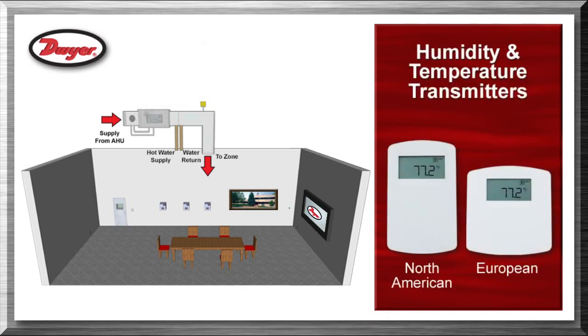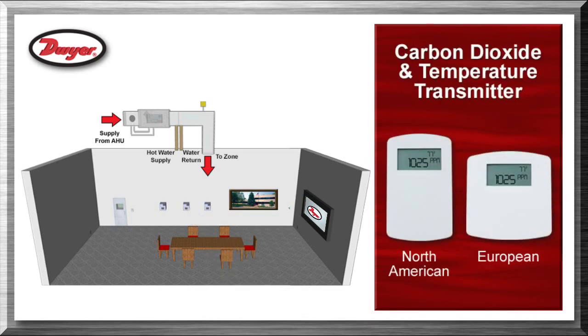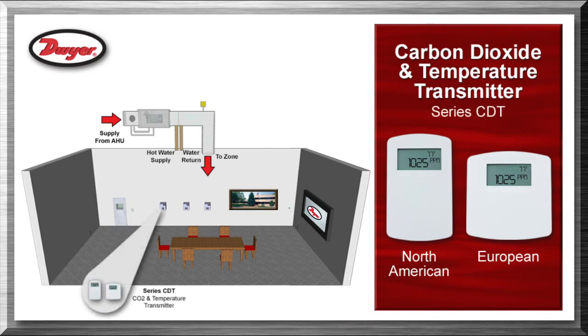Humidity and temperature transmitters, series RHP, are wall-mounted in the zone and used to monitor the zone air conditions and determine demand. Carbon dioxide and temperature transmitters, series CDT, are wall-mounted in the zone and used to monitor the concentration of carbon dioxide to determine the occupancy in the zone. The amount of airflow to the zone is then varied based on the occupancy.